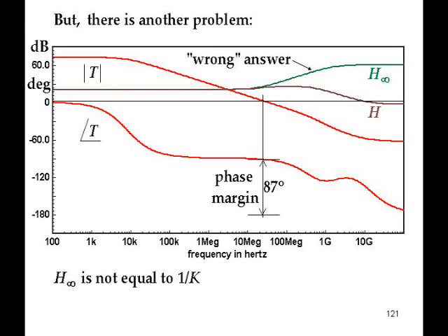In fact, in that circuit, R2 and R1 constitute the divider ratio. The ratio is 10 or 20 dB flat. So H infinity for that circuit ought to be flat at plus 20 dB. And the H infinity is the top graph in that picture, and it's not flat.